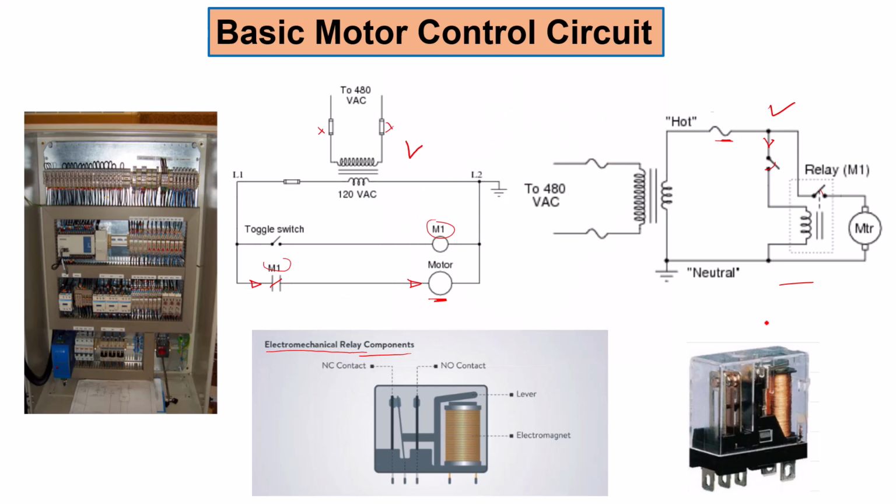Okay, now, so that's basically the operation here. So the relay is energized, a contact closes, and the motor will start turning. So it performs the same operation as the one on the left. Now we all agree that these two diagrams perform the same functions, but we know that there are always advantages and disadvantages to whichever control circuit you want to implement.